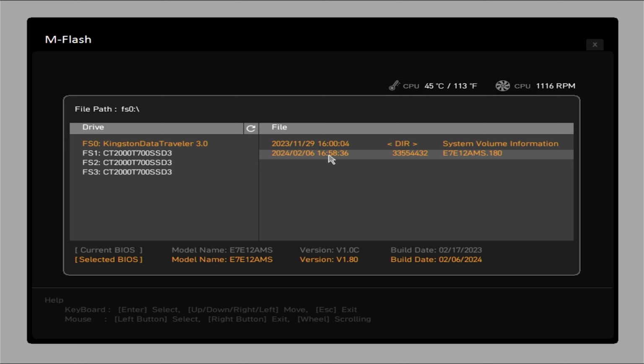But what you want to do is PWM, because PWM actually sends intermittent voltages, and it can result in a quieter operation, and it also allows your fan to spin at lower speeds as well. So definitely make sure that your case fans are PWM if they are 4-pin. So you want to make sure that they have 4 pins on them, and that means that they are PWM compatible. If they're just 3-pin, then you want to use DC mode because that will send a direct voltage to them.